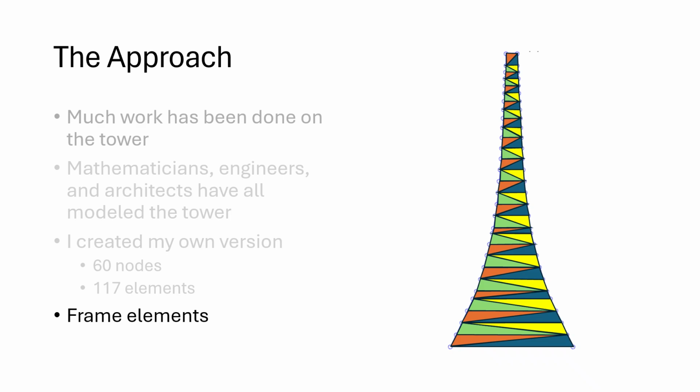I briefly considered using constant strain triangular, or CST, elements, but I quickly scratched that idea. I think I only picked that because it would have been convenient based on the geometry of my elements and the natural triangular shape that they took. But my experience showed through, because I would have mistakenly modeled what could have been modeled incorrectly as a plate instead of using a lattice joint structure like it really is. So I'm glad I didn't see that work through.